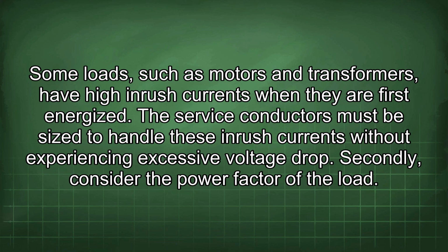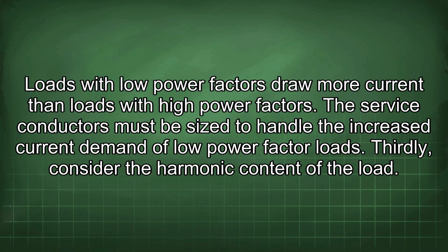Secondly, consider the power factor of the load. Loads with low power factors draw more current than loads with high power factors. The service conductors must be sized to handle the increased current demand of low power factor loads.